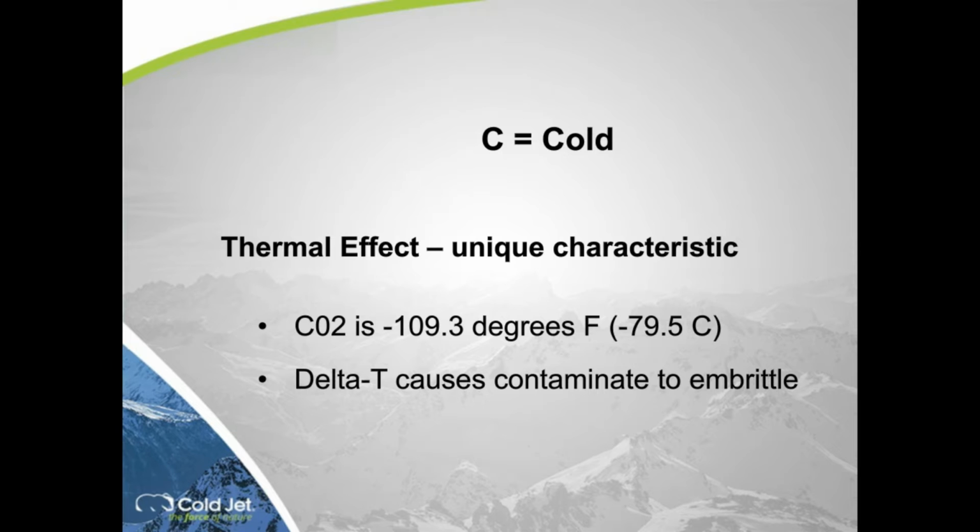That dry ice will impact the contaminant. It will cause that contaminant to embrittle. It'll cause it to freeze, and it'll lose its bond strength. It'll lose its adhesion because it just got instantly frozen, and it just frees it up from the substrate. So you have cracked that contaminant with a little bit of kinetic energy. You freeze it, and then it lets loose.